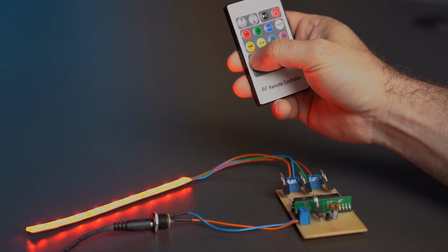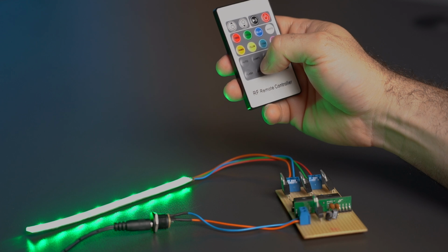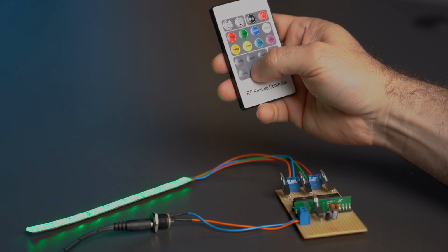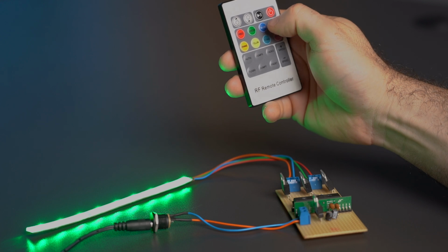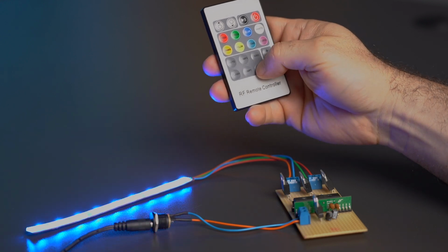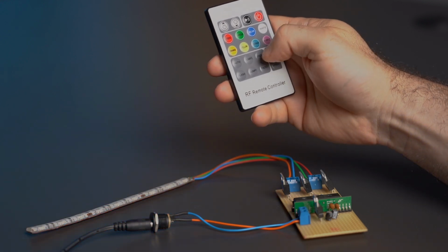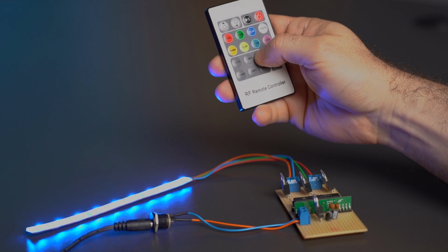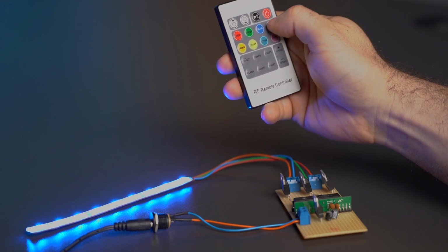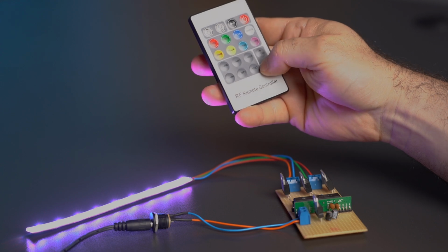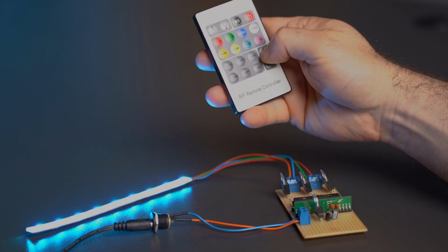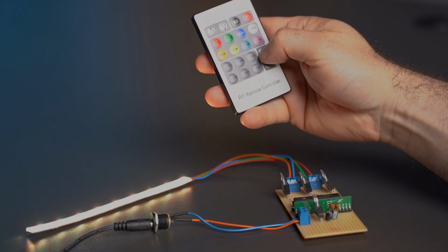This device can be used to control 12-volt LED strips. There are 3 LEDs in a small case, one red, one green, and one blue. Their anodes have a shared output, but all 3 have their cathodes out, so each color can be operated separately. If you control the brightness of the 3 primary colors with a PWM signal, you can mix several colors from them. The circuit is controlled by radio remote control,